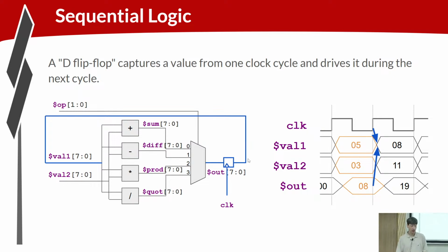So everything that we do in Transaction-Level Verilog, TL-Verilog is going to manage the sequential elements for us, the flip-flops. Okay, everything that we're going to imply in our design is a D-type flip-flop, which is simply taking the input and carrying that forward to the output. There are other types of flip-flops that incorporate logic functions. Logic synthesis is very good at taking the functionality of our circuit and optimizing it to choose logic gates that are optimal. If it's optimal to choose a different flip-flop type that incorporates some of this logic, logic synthesis will do that.